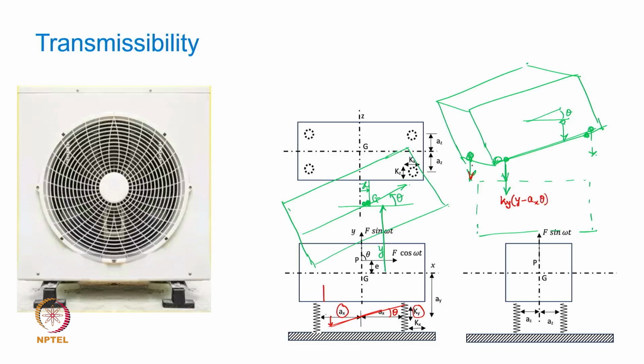Will this be the same force? Yeah, because this body is tilting like this and we are considering only one planar motion. So when it pitches, both the springs are displaced with the same displacement. The net stretch in the left two springs is going to be the same. This unit is going to simply tilt like that. So there is no doubt about this force being identical to the front one. You think about it if you have any confusion on this.